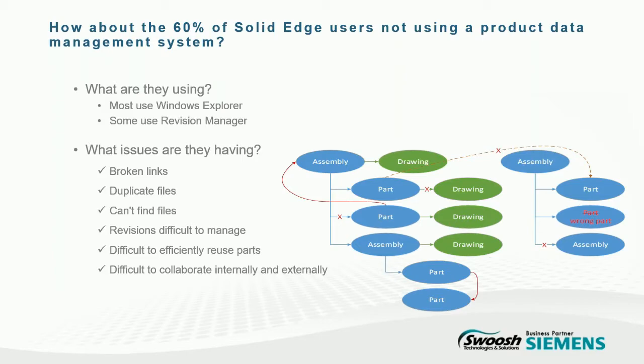anybody who's used a parametric CAD system, and it's not just us, SolidWorks and Inventor too, you have parts, assemblies, sheet metal parts, drafts, things that are linked together, and you start renaming things, moving things around just randomly. When you open up an assembly and draft, you're going to be missing things. So you have to be really diligent in the way you're doing this.